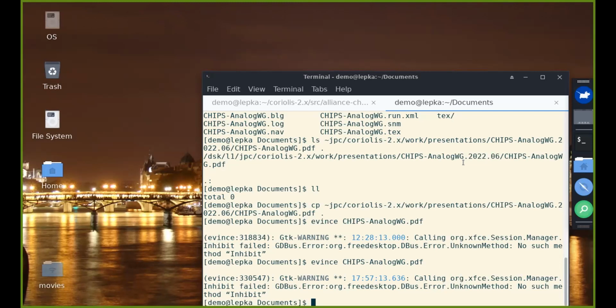And then how do you decide what you think is the best placement ahead of time, right? That's not what you do in your flow now? I mean, we would have that graph, right? You have width versus height. We would have area versus wire length on a graph, and then we would choose which placement we like based on being Pareto in that space. Yes, that could be done. It's not very complicated to implement. Okay.